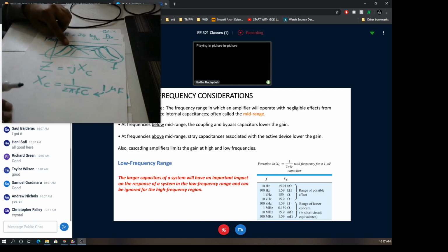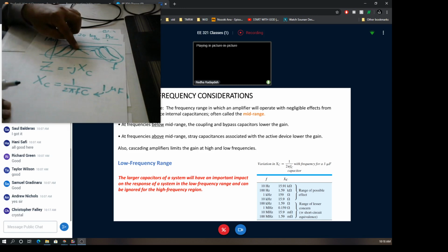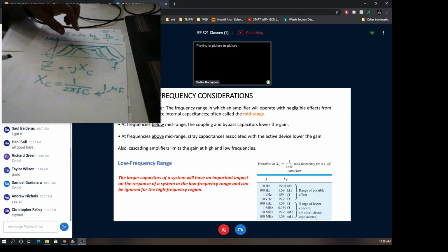Okay. The second one down represents the frequency response of another amplifier, or the second stage. We have a cascaded structure. The third one here represents the frequency response of the third stage individually. We said that when you cascade them, when you connect them in order to produce a cascaded amplifier, the frequency response of the cascaded structure will be determined by the intersection of these three frequency responses.